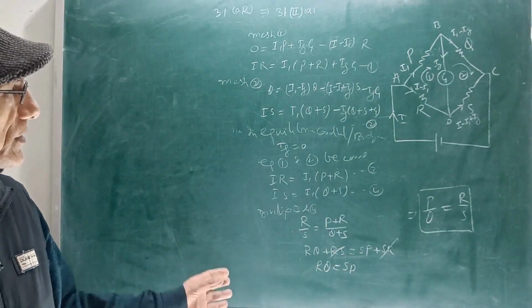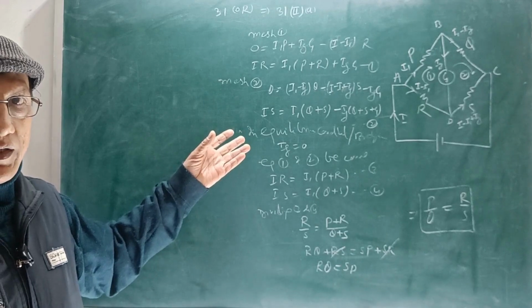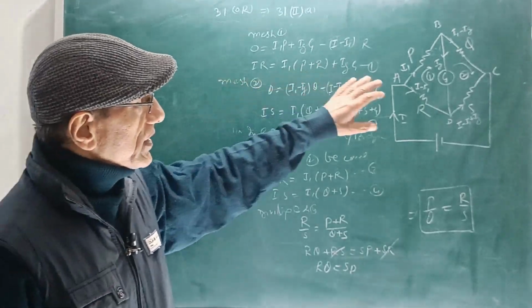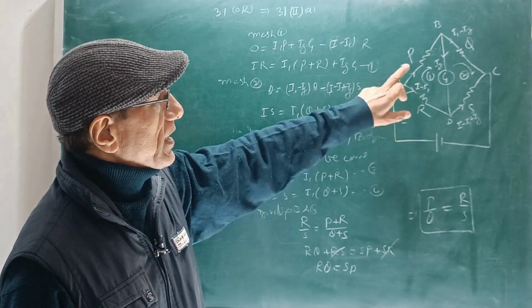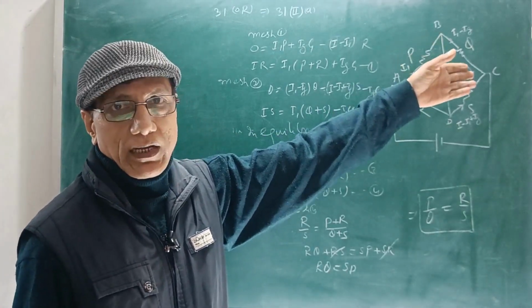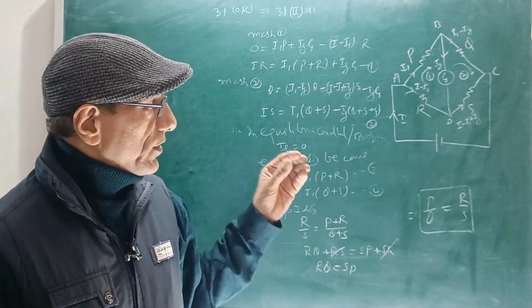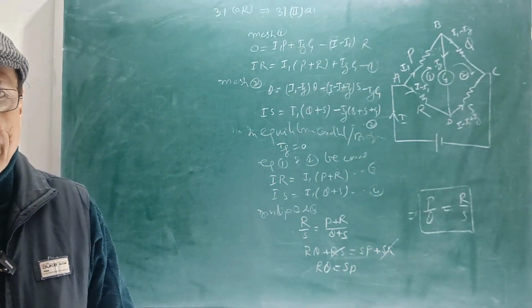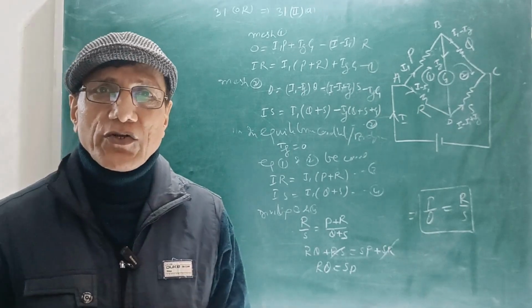किरचॉफ्स लॉस यूज करने पहले जंक्शन रूल यूज करिए और कोशिश करिए मिनिमम नंबर में. बच्चे क्या करते हैं, यहाँ I1 ले लें, यहाँ I2 ले लेते हैं, यहाँ फिर Ig हो गया, फिर वो और नया, उससे फिर कॉम्प्लिकेटेड हो जाता है. तो कीप द लीस्ट नंबर ऑफ वेरिएबल्स यूजिंग जंक्शन रूल.